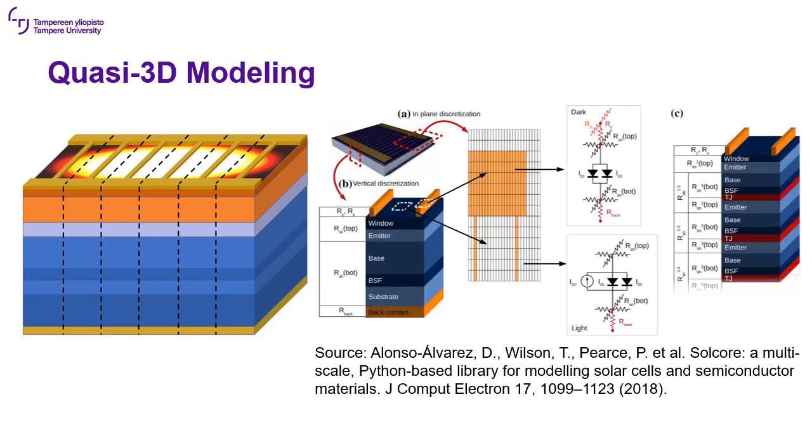These submatrices and double diode model are then inserted into the Quasi-3D solver, which discretizes the cell relative to the illumination and grid profile matrices, such that all these subcells are connected to each other with resistors, which model the lateral current flow of the photovoltaic device.